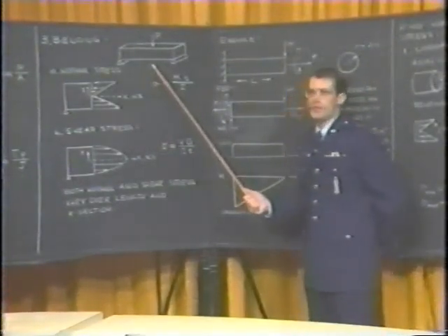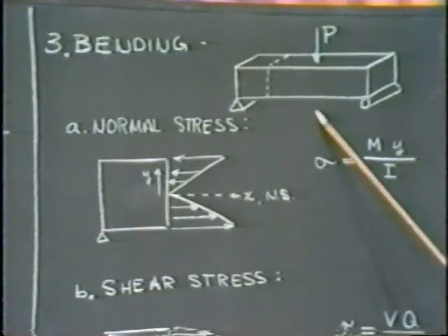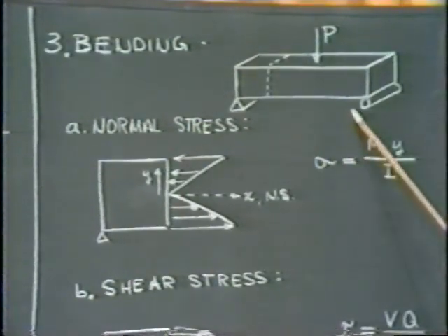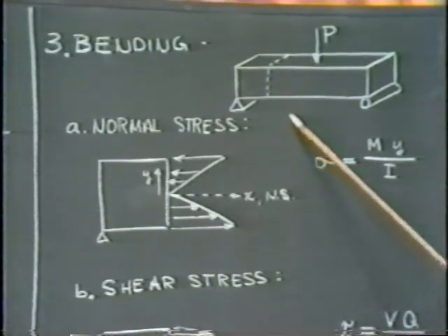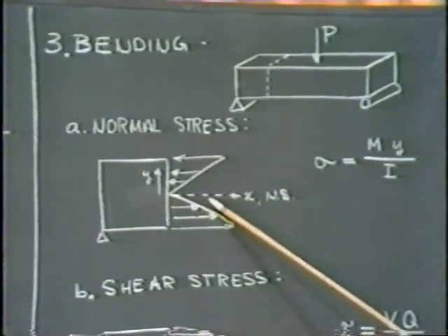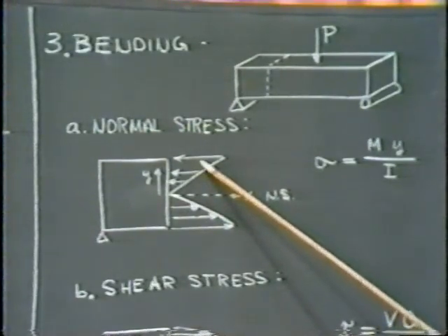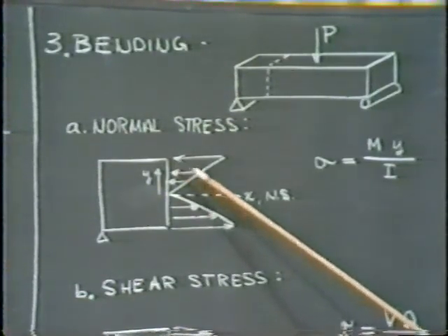For this picture, I can imagine what the bending moment diagram would look like, strictly due to practice. I know that the beam would experience a positive bending moment throughout its length. I have used that rationale to explain my picture down below here. A positive bending moment would place the top fibers of our beam in compression, and I've represented that by an arrow, perhaps suggesting it's pressing against the exposed area.